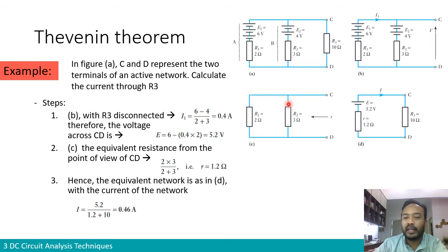Just a connected wire like this, so you can calculate the equivalent resistor. So here it's pretty simple. It's the parallel equivalent resistor. Therefore, you will end up with an equivalent voltage generator with a voltage source of E and internal resistor of R. And then, of course, in order to calculate R, you can use your loop to do your KVL and find the current as written in this example.